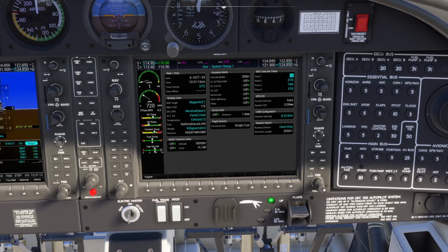feet, and we can set them to on. I don't think you can in this system, but then you want these onto auto 8.33, and you can set 1800 feet on the runway length and enter.